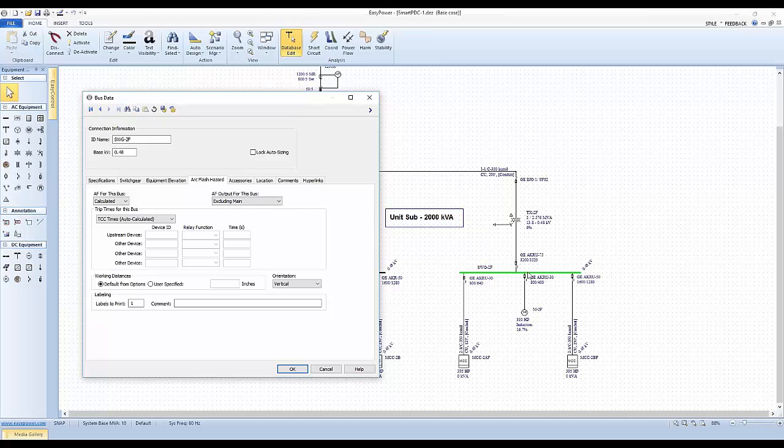All right, and so we'll talk about this again, but that's the primary purpose for this selection. So in this particular case, we realize there's no barrier between the incoming cables and someone working on the hot bus. Now, in more recent equipment or more recent breakers, there are barriers here, in which case I can include it, or if this breaker itself is in a separate cabinet or a separate section where there's a barrier between its upstream connections and the main bus, then we can include it. So, with that said, let's go on a little bit further.